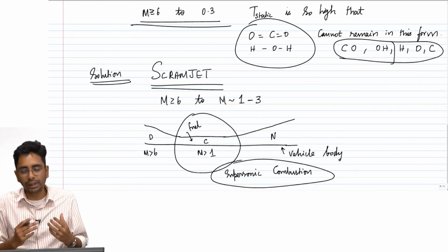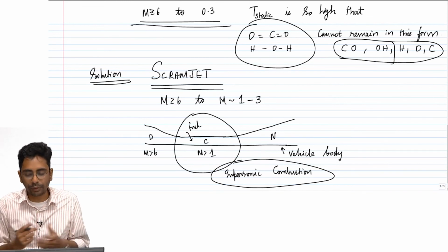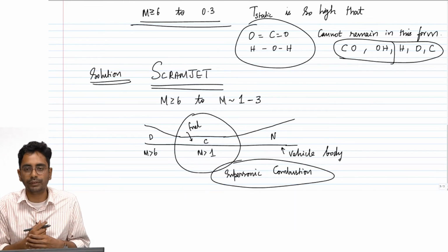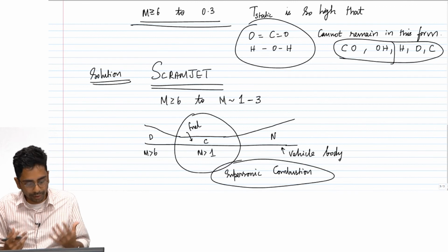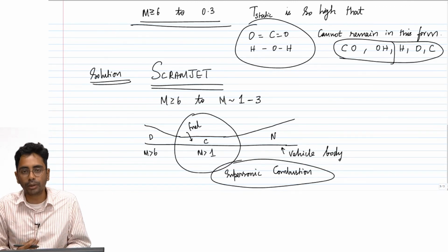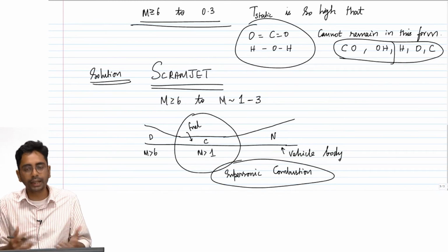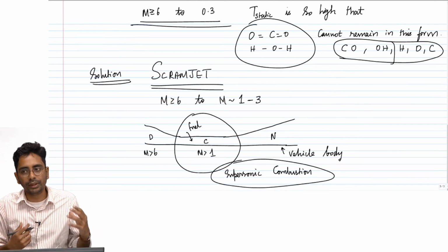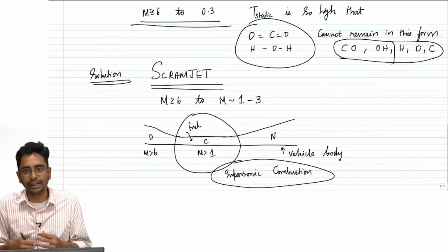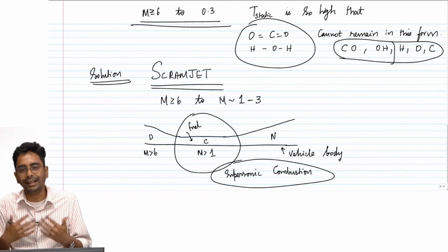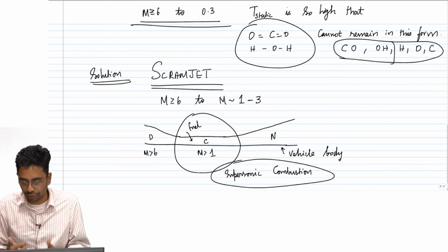And again, in principle, no rotating parts, therefore there is a lot of simplification of the propulsion device, but there are very difficult challenges brought about by the fact that the combustion should be conducted under supersonic conditions, and additional challenges because you have a vehicle made of metal flying at Mach 6, and the heat loads or the heat flux that comes to the surfaces and how it is dealt with, how the cooling is done, everything is a very big challenge.